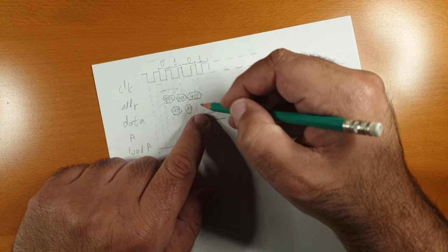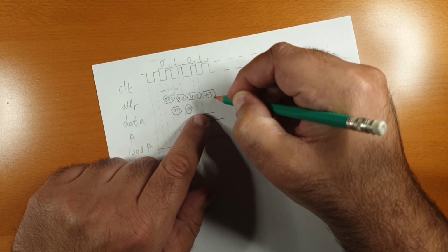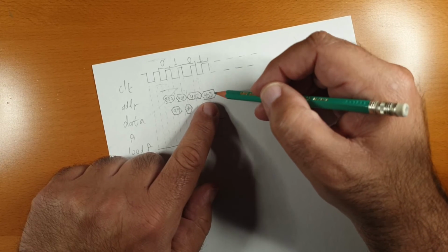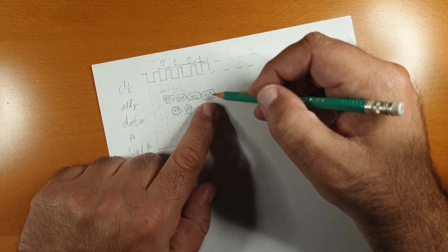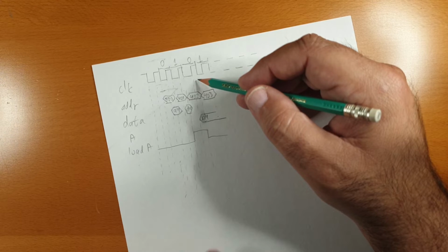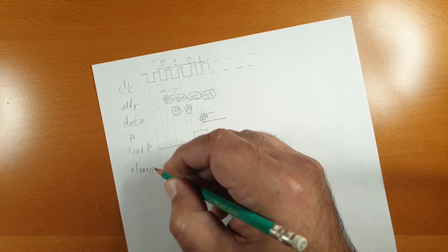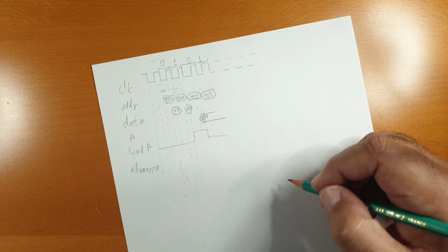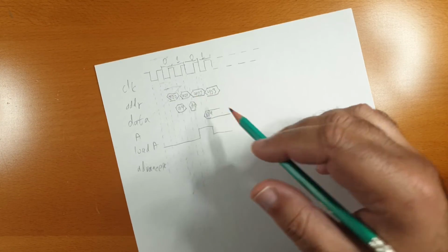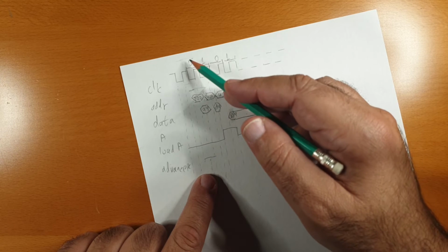So whatever is the next opcode, cycle 1 will be reading from 403. Well, it might be reading from somewhere independent, but the program counter needs to be 403. But wait, the program counter updates on the falling edge of the clock, which means that if we're to list the advanced PC control line, for it to advance from 400 to 401, it needs to be high during cycle 0 of this opcode.